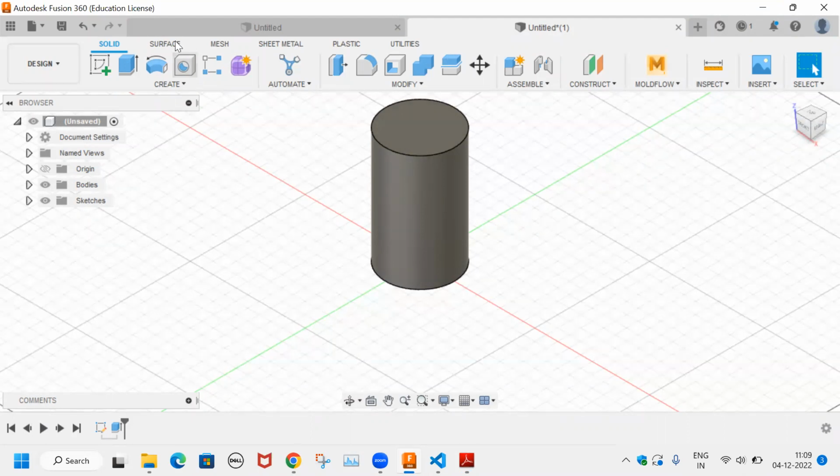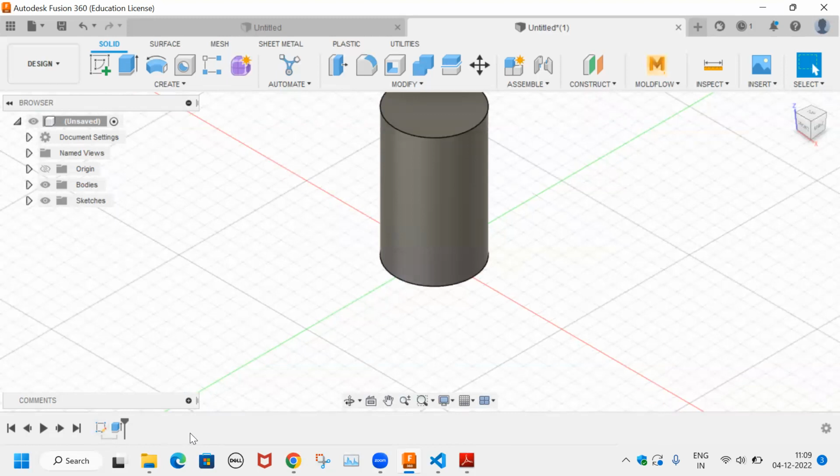And then you use various modeling features like extrude, revolve, sweep, cut, etc. to build 3D features. For example, in this case, you can draw a circle and then extrude it to get a cylinder. And in the model design tree, you can see that there is a sketch that's drawn on the XY plane. And then there is a cylinder that's being extruded using the extrude feature.